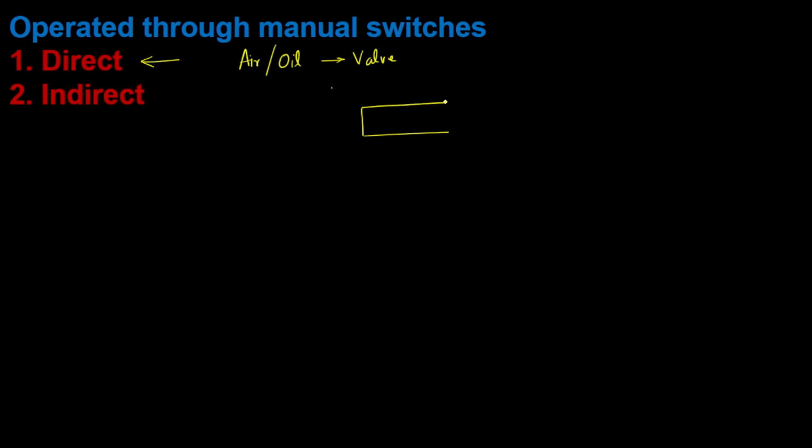So this is, you can make a rectangle box with a line and horizontal line. This represents a double acting cylinder, and for this double acting cylinder there are two ports. Let us say port A and port B. So now for forward motion, if you wanted to move this cylinder forward, for this direction the air or the fluid should enter into A.